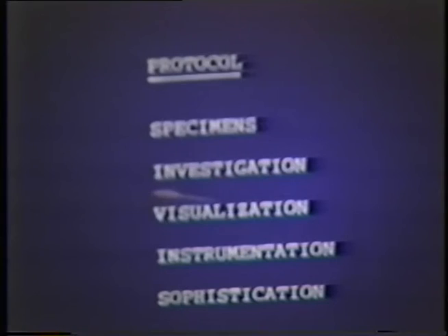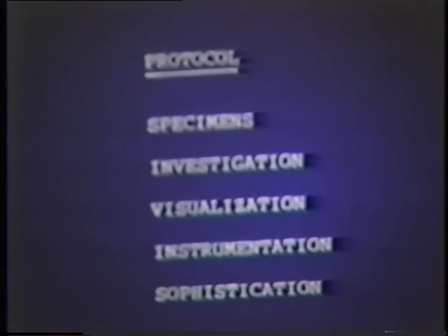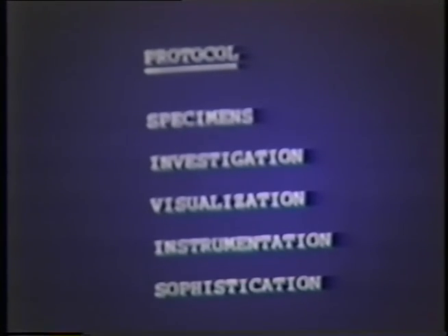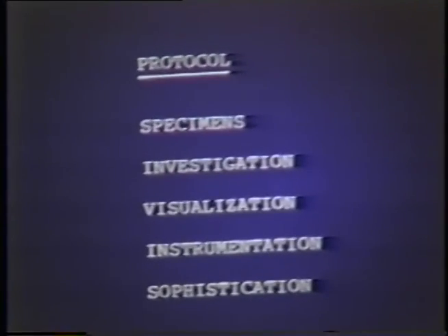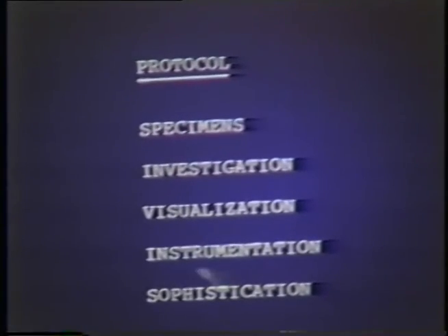Make sure you know what instrumentation you've got. If you've got an old microprobe, you may only have light optics, which is going to limit your spatial morphological resolution. You've got to make sure whether you're working with a transmission microscope, because it then means you can only work with thin sections. If you have a scanning beam instrumentation, then you can work with both thin sections and bulk samples. And of course, some degree of sophistication. The next few slides will amplify on this.